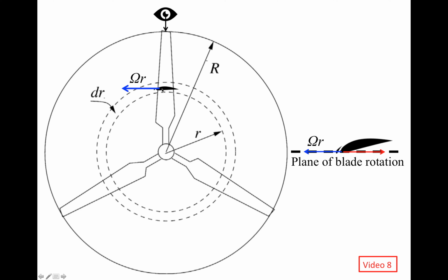And we were discussing the linear velocity, right? Suppose the rotor actually goes this way, then the linear velocity of this particular airfoil is capital Omega, that's the rotational speed, the angular speed, times the radius r. So the linear velocity is just capital Omega multiplying r. That's the case if we do not consider the angular induction. If we consider angular induction, it's going to be slightly bigger, right? It is obvious that this linear velocity increases with radius. So as we move from the root of the blade to the tip, this linear velocity is going to increase.